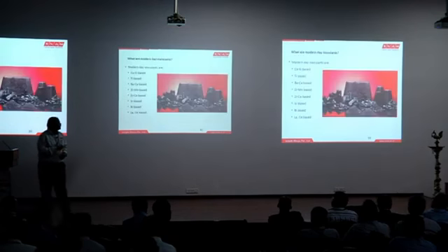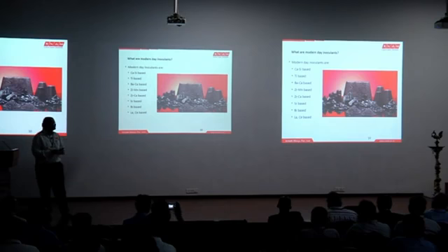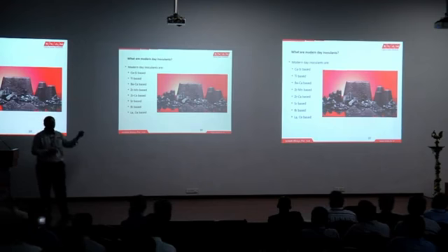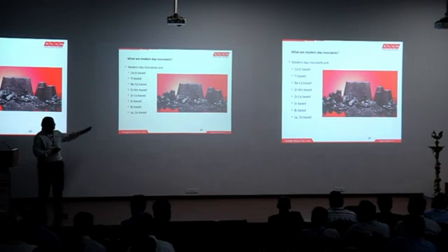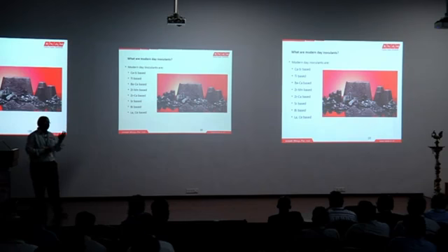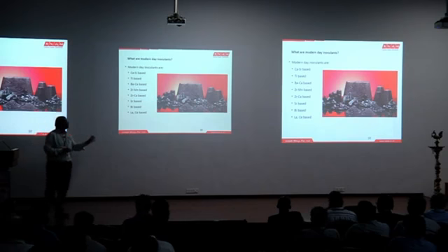So these are the different modern-day inoculants available. These elemental combinations, either individually or in combination with other elements, are being used in today's foundry industry to manufacture the thinnest to the thickest castings available today. All of these are ferrosilicon based. You add iron silicon to it, which may contribute 60 to 70% of the total weight, and the balance will be these elements.